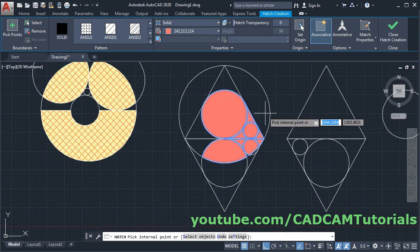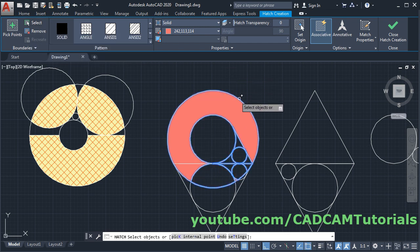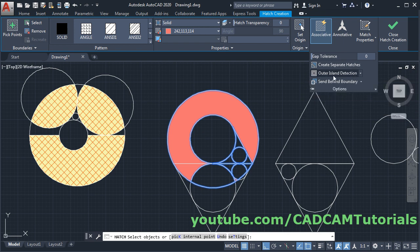And if you want to create a hatch by selecting objects, then for that you will have to click on this select boundary objects. Click on it and select the object inside which you want to create the hatch. Now after selecting this circle, it has changed the hatch area. Now you can control your hatch area by clicking on these options here. Right now outer island detection is selected, therefore it has created hatch for the outer objects.